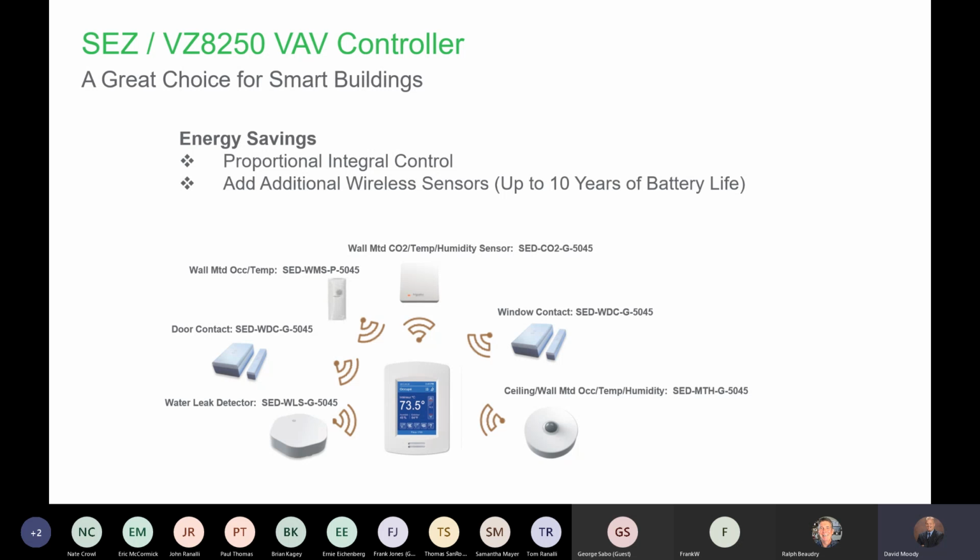You can actually write a little Lua program and load it inside of this device and have it look at the occupancy and say, if I'm occupied, then consider the temperature in this room. You could go through and look at all 20 of those and say, I want a high, I want a low, I want an average, I want a medium, whatever you'd want to do. At that point, it just becomes a mathematical selection of what device or what room you want to use to control that VAV box.